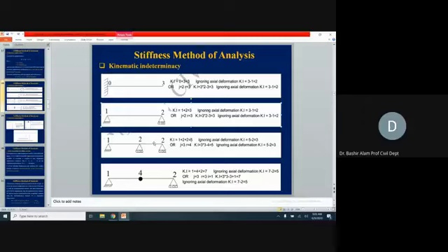Now, if we see that this is a beam problem, axial effects are not going to be significant, so we can ignore the axial effects. Now, by removing the axial effects, what do we mean? We need to take simply the number of members from here, which are 2. So this is becoming a 3 degrees indeterminate problem. And when we solve this, we need to identify those 3 degrees, and those 3 degrees will be rotation at the left support, rotation at the middle support, and rotation at the right support. Those will be the indeterminacy, and those will become our unknown quantities.